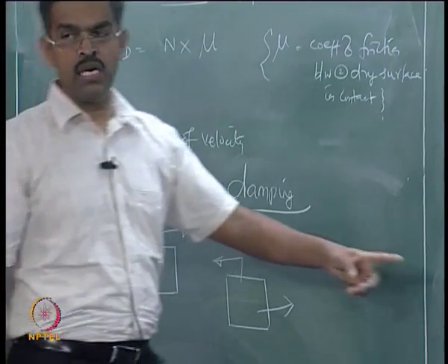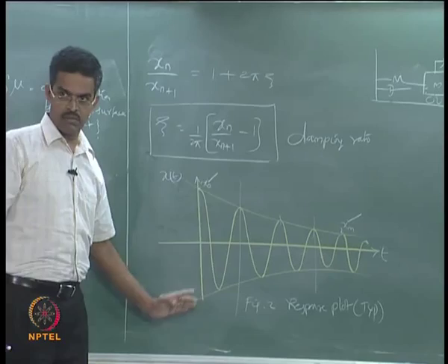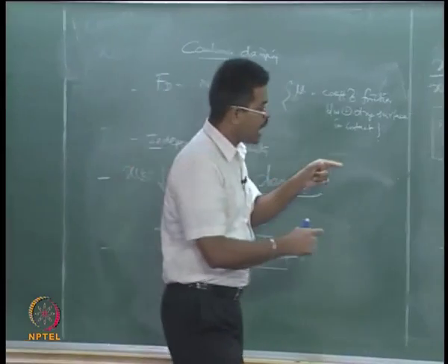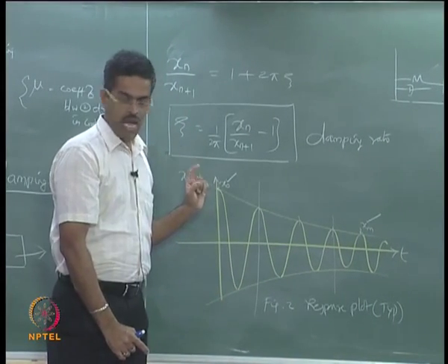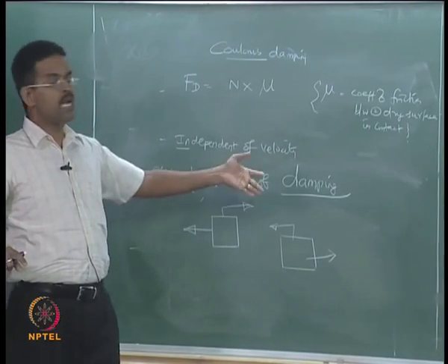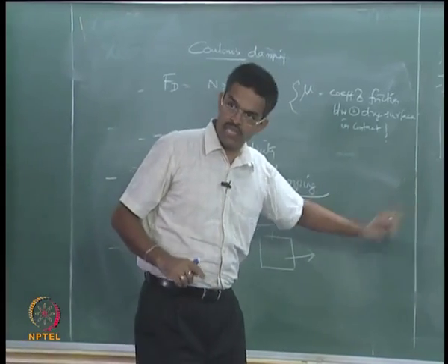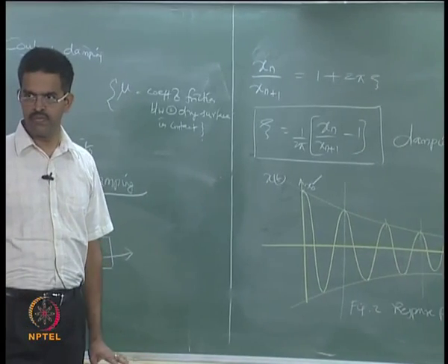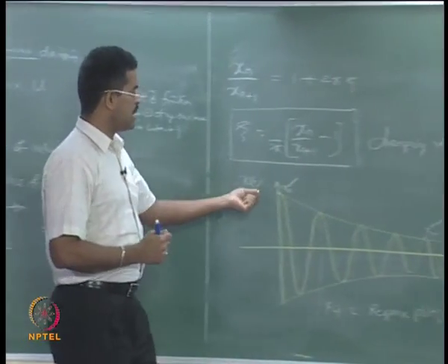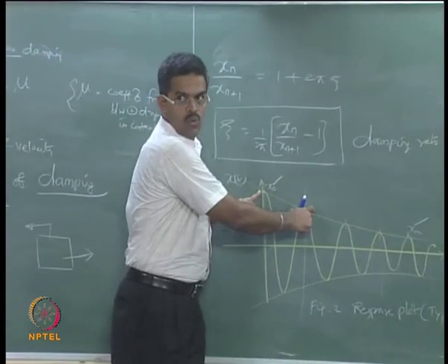And we have very clearly seen here the movement of the body is alternate, somewhere it is moving positive, negative, positive, negative. It means the damping cycle is valid only for half, is it not? After half it changes its sign. Is it clear? We cannot simply apply the damping force for the full cycle, because within one full cycle there is a change of sign happening in the response. So, we must look only at the half cycle first to capture the qualitative variation of the response occurring because of damping. If you capture the full cycle, you will not know.